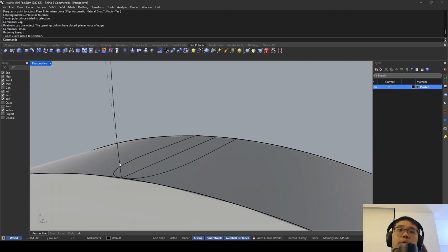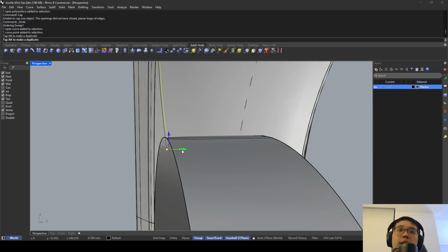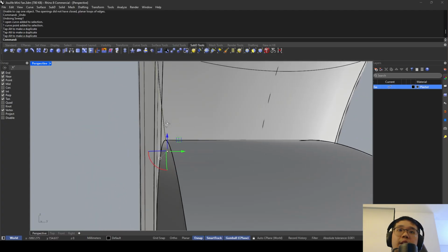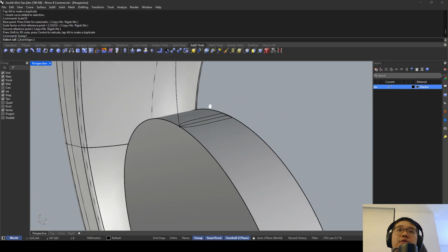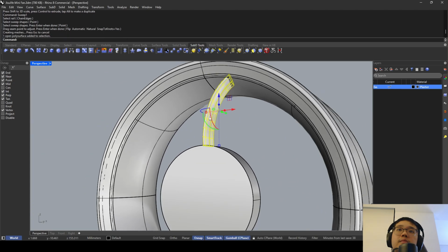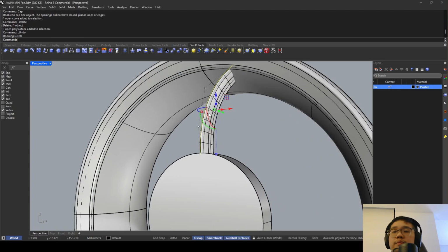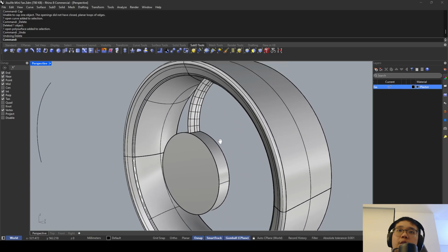So I will take this, move it inwards, down, so that it sits entirely inside the shape. And I will just make this smaller so there's a bit of tolerance. So I can't cap that, that's fine. I'll just leave it. Bring this out by 50 mil so I can keep a copy.